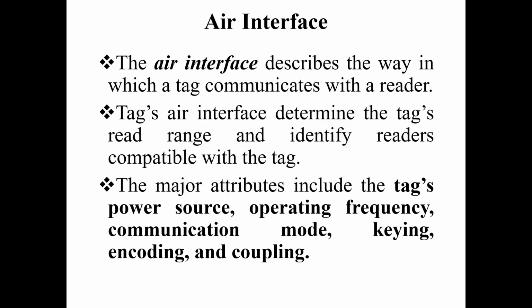The air interface is essentially the language that allows an RFID reader and tag to communicate. It covers power transfer, modulation method, data encoding and anti-collision techniques. The functions of the air interface include power transfer, communication, identification and data exchange.